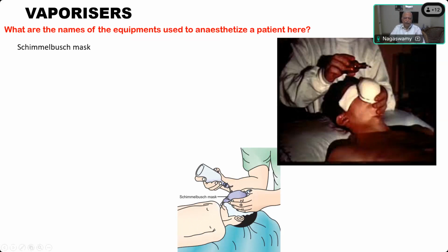Not negative pressure, atmospheric air is sucked into the bottle so that there will be a constant flow. Otherwise, in a tightly closed bottle, if you have only one tube, it will flow a few minutes, then stop. But if you have the second tube, then air will enter and go inside, push the liquid inside, and a constant flow will be there.